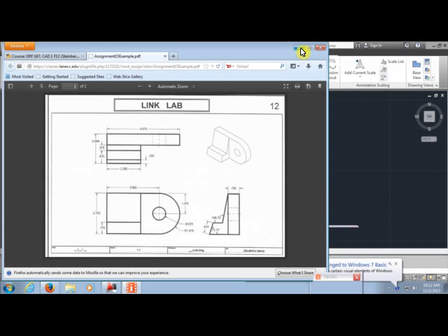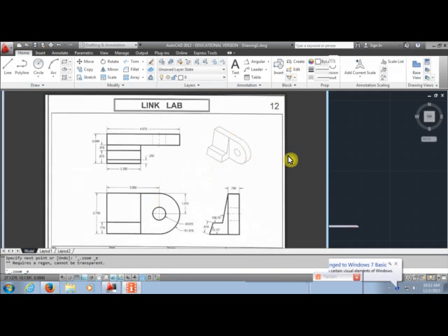So I'm going to go down, and I'm going to go out in this direction, 0.75, enter. And then I'm going to do the same thing at the bottom from this edge, 0.75, enter. And at this point I could close it off, but I don't want to because I'm going to create my arc.